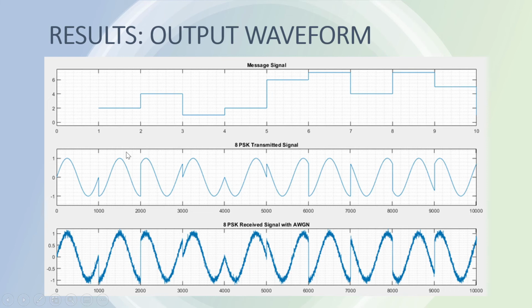So from here to here, you can see that the signal phase shifts backwards by 90 degrees. Then from here to here, there is a decrease by 3. 3 times 45 equals 135 degrees. Therefore, from here to here, the signal moves forwards by 135 degrees, and so forth.